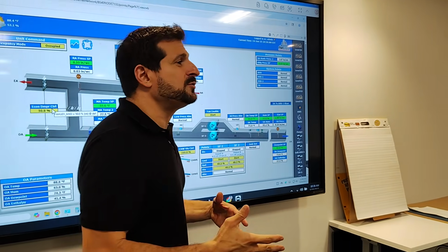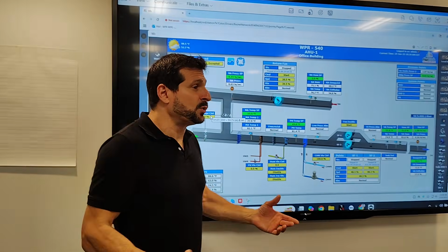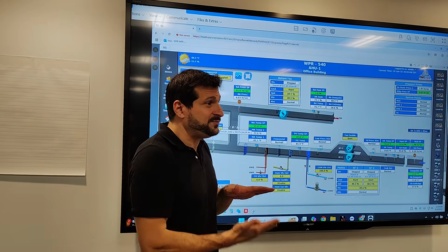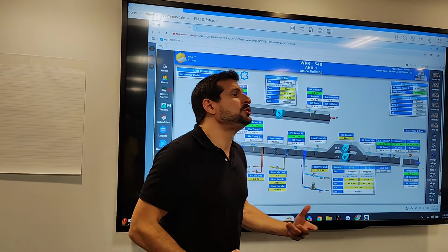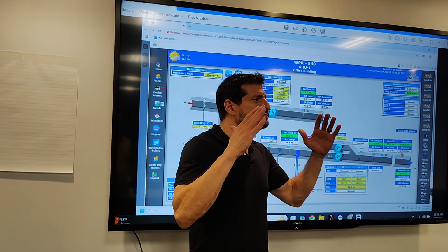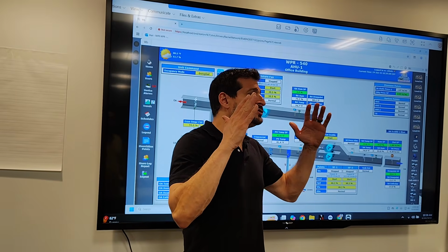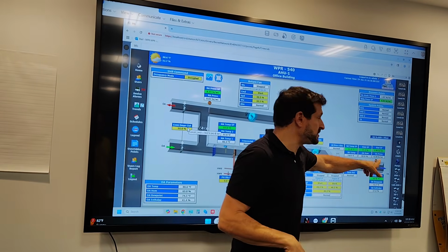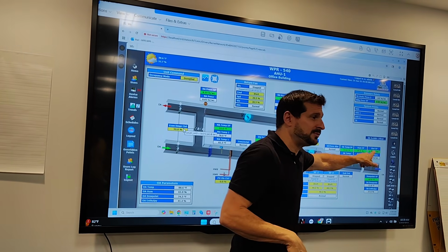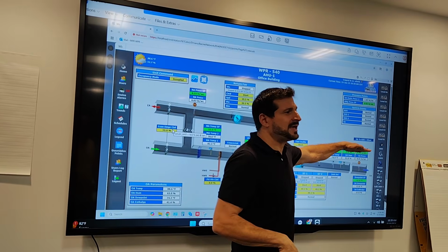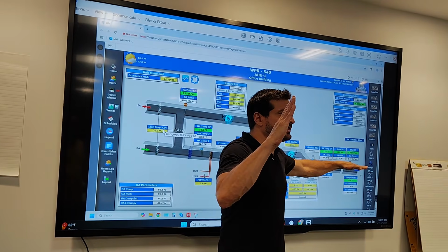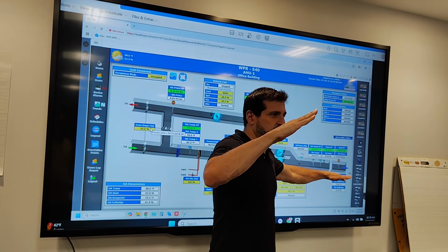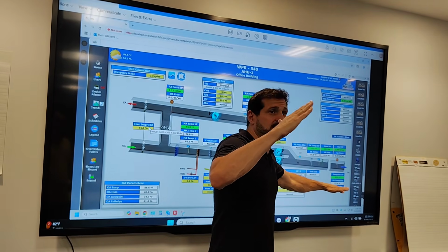Now, here's what you do if you want to really be smart about it. After you have all the VAVs online, and you know the damper positions of all the VAVs, you look at them. And you say, hey, are all my VAVs mostly closed? If all my VAVs are mostly closed, then that means the VAVs are holding back my fan. Start dropping this. And you don't make this user adjustable anymore. You make this a program. Now the program says, drop it down to 1.8. And look at the VAV dampers. They're still mostly closed. Drop it down to 1.7. Look at the VAV dampers. They're starting to open. Drop it down to 1.6. Look at the VAV dampers.